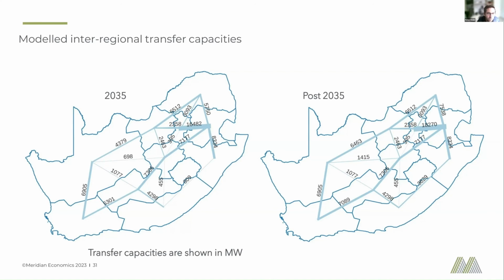But definitely these are all scenarios that you can test in these kinds of models. You can force different levels of pump storage in and then look at what that does to your objective function. You can look at how the system dynamics change. Who knows, once we move away from the single node model to the multi-node model, there might be more localized benefits of doing different storage in different regions. So tons of interesting stuff to explore. And at the moment, this is just a framework where you can start to test these kinds of hypotheses.